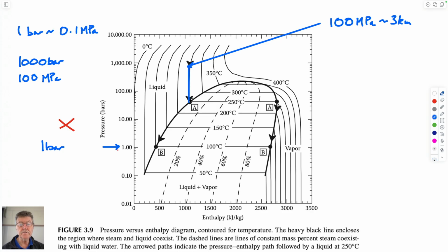So you come down to this point as a liquid, and then you have to make a decision as to whether it goes down on this path, whether it can climb here and go across the top, which of course it can't because it has to have some energy put into the system, or whether it changes so quickly that it doesn't have time to change its enthalpy or the pressure that's acting in the system. Can't lose energy from the system. So the chances are that if it's brought up to the surface very quickly, it will come up with this amount of enthalpy in it, which is the amount that is existing in native form.